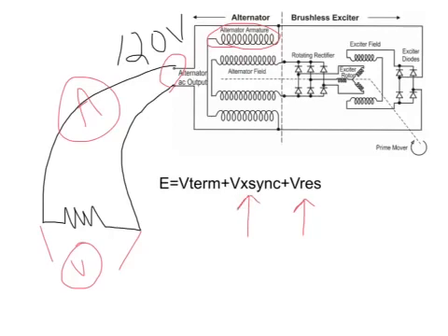So when we take our entire voltage drop due to our in-phase component, add to that the voltage drop due to our entire out-of-phase component, and add to that our terminal voltage, that gives us what we were required to generate in order to get the terminal voltage. In this case, let's say our voltage drop due to resistance was 2 volts and our voltage drop due to synchronous reactance was 4 volts.